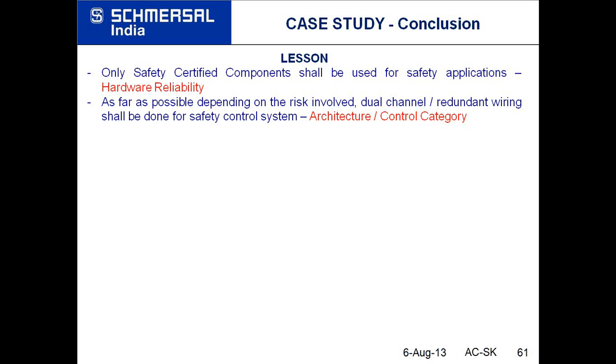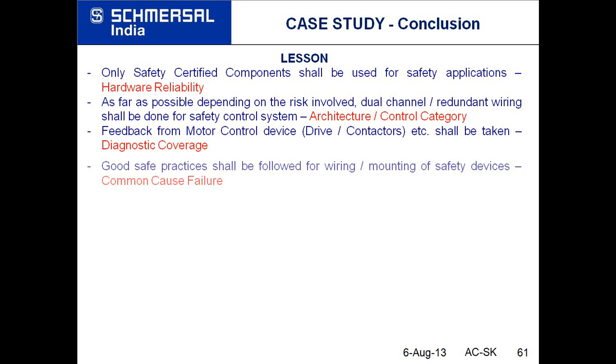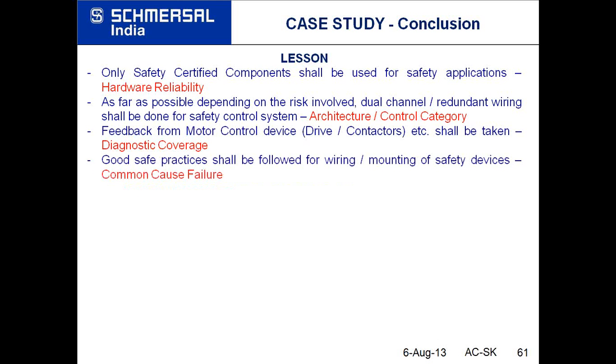The third lesson we learned is that we should have feedback from the motor control device, which increases the diagnostic coverage. And good safe practices shall be followed for wiring or mounting of safety devices to take care of common cause failure in the system.